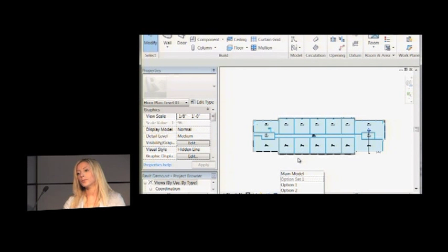Also, if you're running into problems with your model, always try saving it to the C drive before you export. It could be that you have something weird in the character path that's causing an issue during the export. Of course, drop it right back on the network because IT will hate me for saying to save anything onto your main computer. But sometimes just doing that, you'll see that it's an issue with something that's happening, or a character, or even something like a money symbol in a path can cause these types of things to happen.